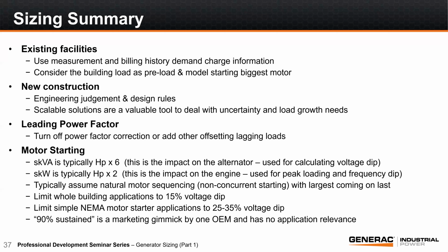If you don't have Power Design Pro, we do have a document that will show you how each generator will derate. So it will give you a percentage that you would be able to subtract from the output of the generator to determine exactly at that elevation that you're using it at, what that output for the generator will be. Great. Are there other common factors that may require derating other than altitude and temperature? Not that I can think of, John.